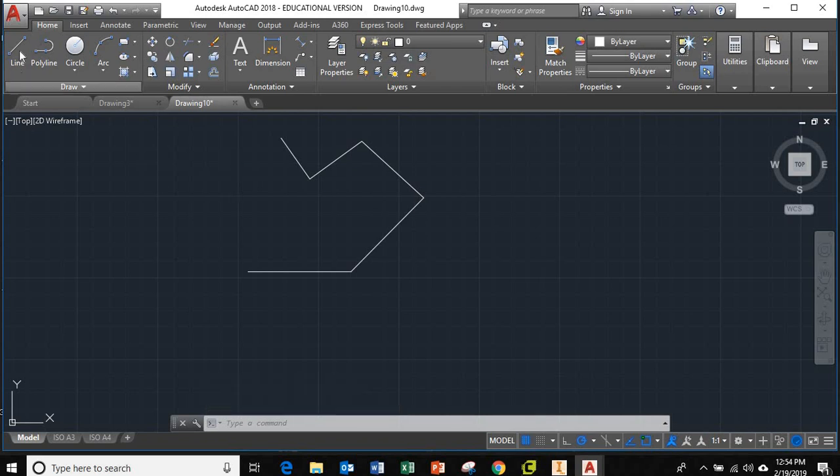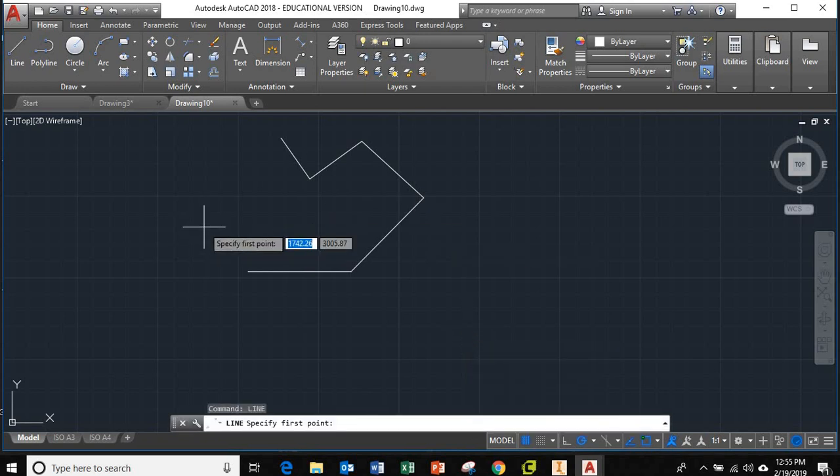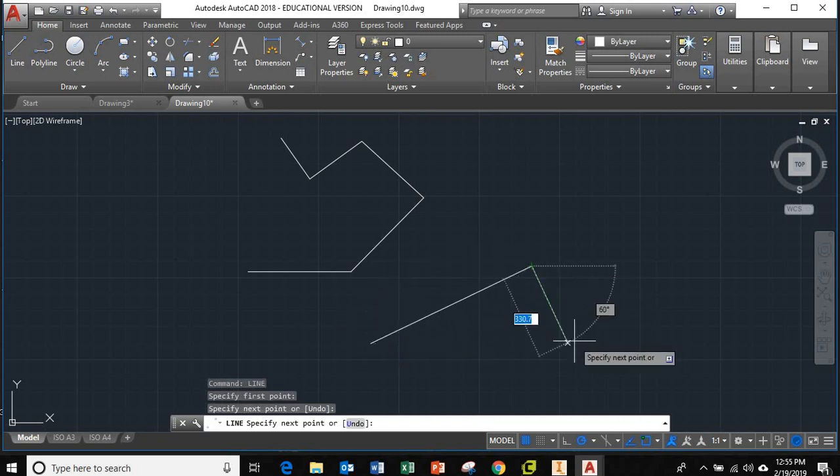Okay, so I started the line command by clicking here. Another thing that you want to know in AutoCAD is a common way to start the commands is by typing them on the keyboard. So if I want to start a line on the keyboard, just start typing line, L-I-N-E, and notice line comes up. If I hit enter, well, now I'm in the line command here, and this command prompt tells me that. All right, so I could draw a line at this point. Okay. Now, I'll click escape to get out of that.